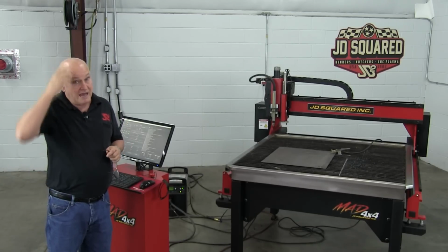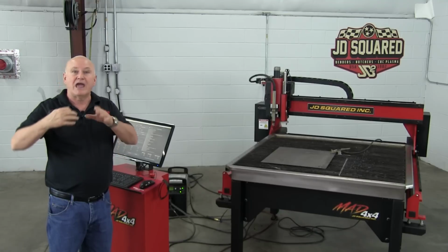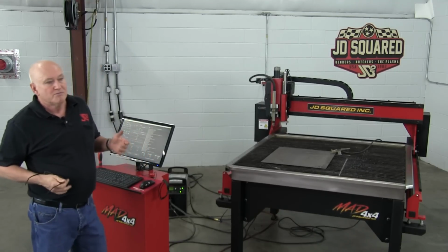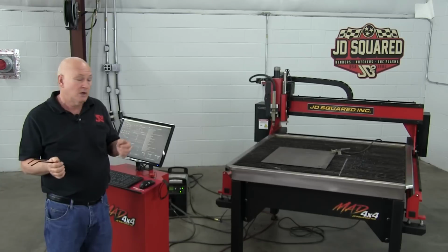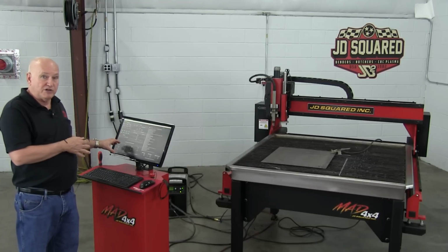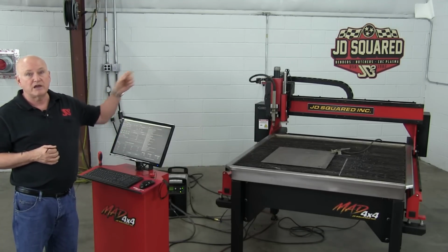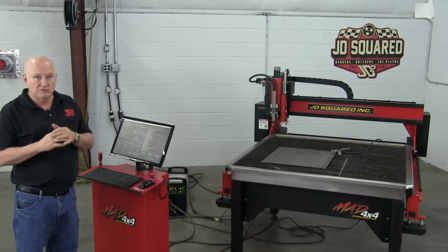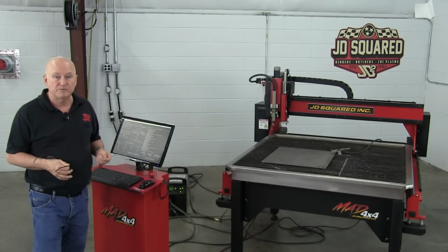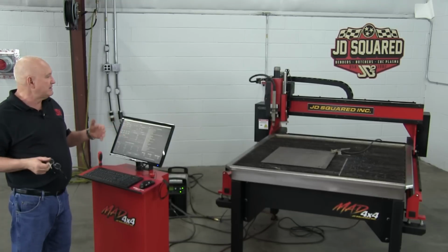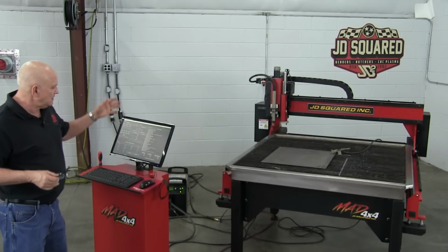What happened? What happened is you hit it with too much amperage and the kerf width increased. So now you know why kerf width is important. So it's incredibly important to make sure that what we're telling the machine we have here and what you generated in your CAM program are the exact same values. If they are not, it's game over. You know, live with what you end up with.